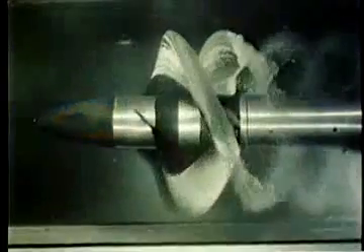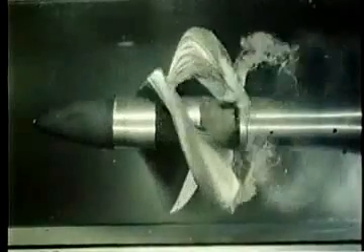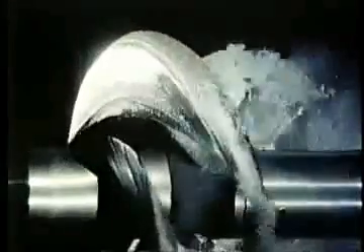Under stroboscopic lighting, we can see that the cavities spring from the leading edge and envelop the entire blade, as in the case of our supercavitating hydrofoil. Cavitation may also occur in hydraulic machinery, such as pumps and turbines. Here is cavitation on the blades of an inducer pump model seen with strobe lighting. Cavitation can also occur in turbulent shear flows because of the local pressure reductions in intense turbulent eddies.